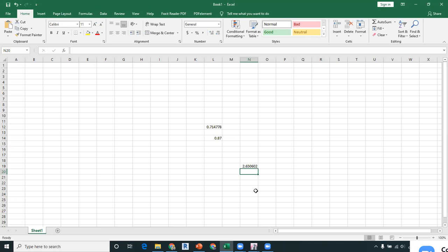So either you have to increase the diameter of the bar for the transverse reinforcement, or you have to increase the number of the legs. Normally the diameter of the bar is not increased because it becomes very uneconomical. The number of the legs is increased, and we provide, for example, this is our beam, and this is the first stirrup, and this is the one bar. For example, this is provided with 4 bars.